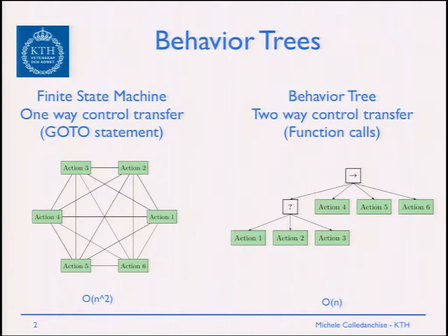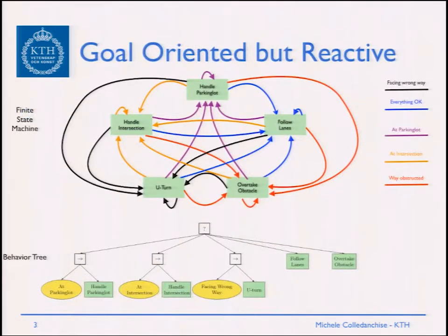We were doing better. And so we believe that one of the advantages of behavior trees is modularity. So we have decided this is neater, especially when it comes to very complex systems. But not only that, since the behavior tree is tick-driven rather than event-driven, and the difference between that is going to be clear in the interactive session, we can have a goal-oriented and reactive behavior. And it's also modular. These three are very important when we have to design a reliable plan.